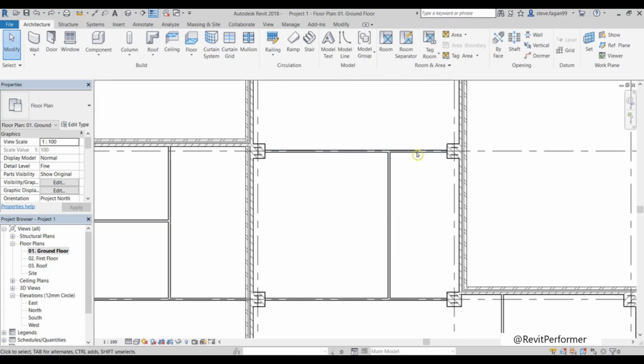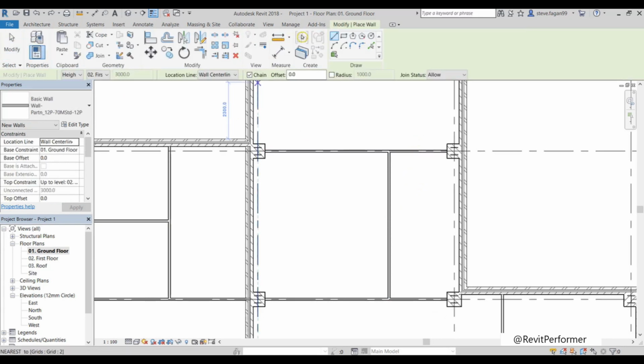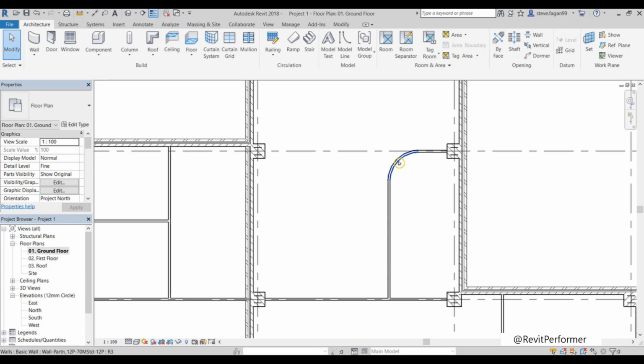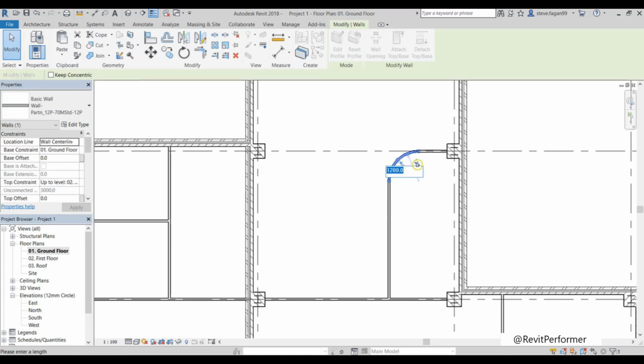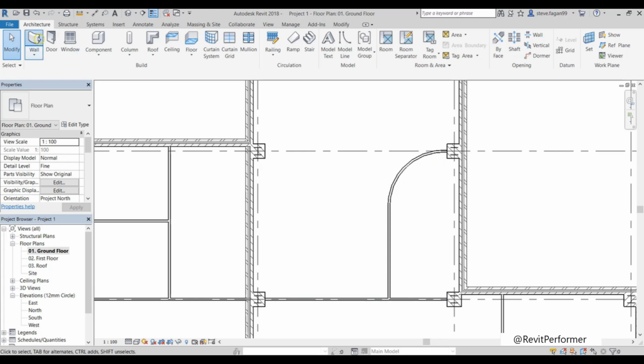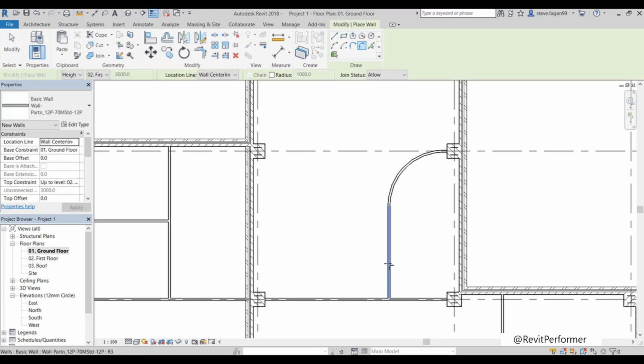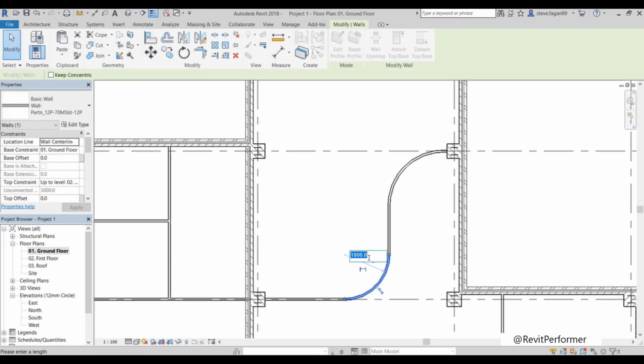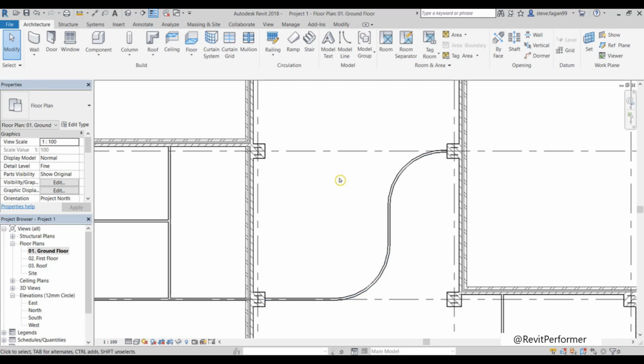Because then I just want to get that curve between the two walls. So go to our wall tool, select fitted arc, select the two walls. If we get that warning symbol, if we just go across to the other side, we can place it and it will generate on the other side. Once it's placed, we can then select it and change the radius, which is 2200. We'll do the same for the bottom, and select 2200. And that's how we generate those nice curves.